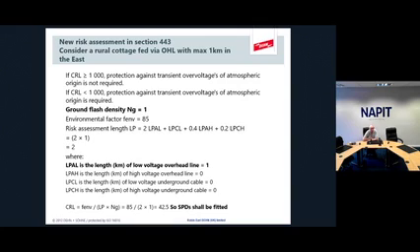And if I was in a cottage down in this valley, it would probably be an overhead line. So I've popped in the value LPAL as being 1. That's the maximum value there. So when I do the calculation for a little cottage in this area, fed by an overhead line, the answer's a mere 42.5. So that would mean I would have to fit an SPD. The biggest factor which would make the difference between fitting it or not is being in the western part of the country and if I'm in a town location.